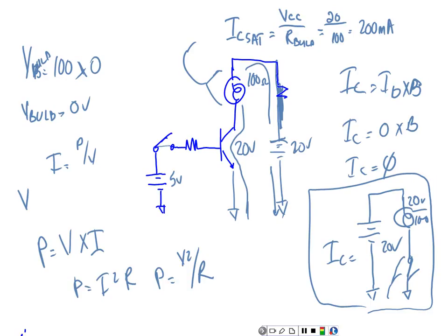Because if there's any deficiency inside that element and you turn it on and hit it with almost no resistance, it takes a short amount of time for the resistance to build up. Have you noticed that? Light bulbs usually blow when you turn them on, or when you bop them real good. They'll turn real bright, because you make those little filament springs bounce, and the two of them touch together, and they're white hot anyway. They just fuse, and then you change the resistance.